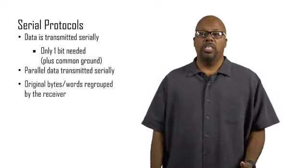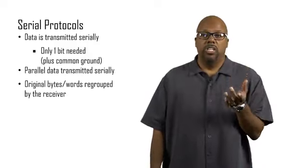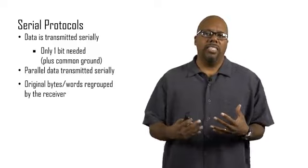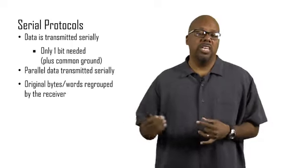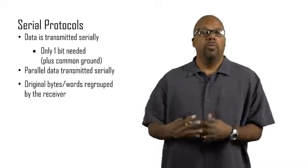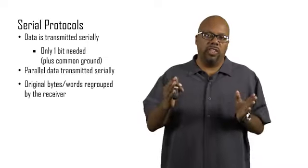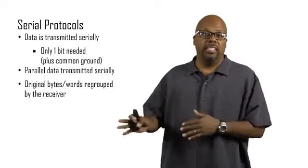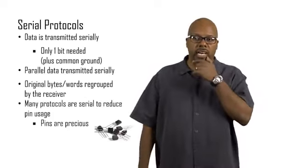The reason we do this is because it saves us pins. What has to happen is these 8 parallel bits are sent one at a time, and at the receiving end, they have to be received one at a time but grouped back into 8 bits. We need the original 8 bits back. So they're received one at a time, and once it gets 8, it says, okay, this is a group of 8, that's a byte, and it sends it off and processes it. So we do this to save pins.